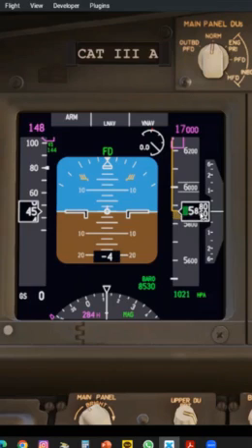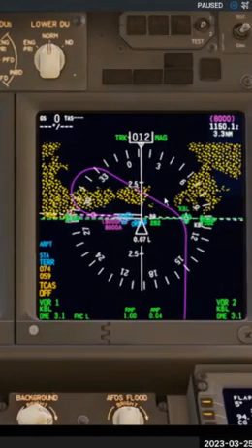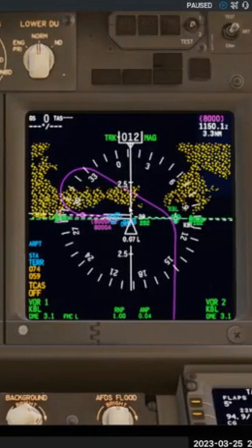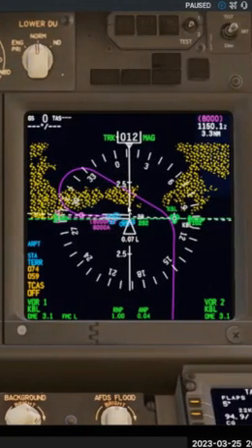Raw data, the altimeter indication, the vertical speed from the IRS, the aircraft symbol reference, angle of attack, compass rose. This represents the raw data that I'm speaking about. On the right side, on the nav display, in this mode, we are looking at computed data.